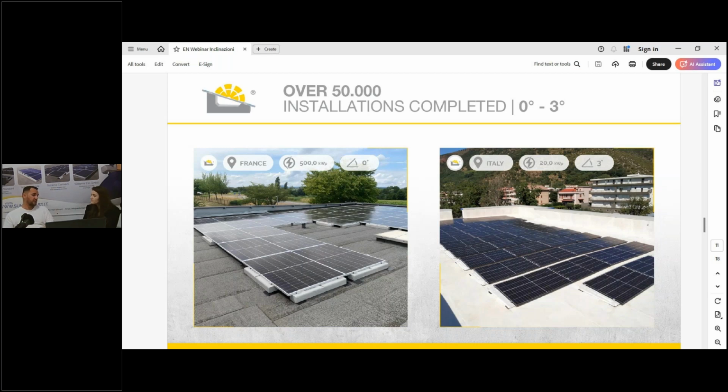It can be used if somebody doesn't want someone else to see it. Landscape. Yeah, or landscaping, or somebody just wants to put it on the roof where nobody can see it from the street. All of these use a lower inclination than this. Zero for me is the perfect solution. Let's say it's a kind of east-west orientation because the panels are next to each other, and even though they don't have an inclination, you can generate a lot of power.